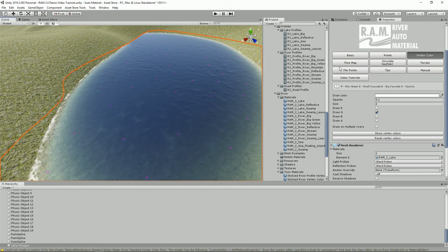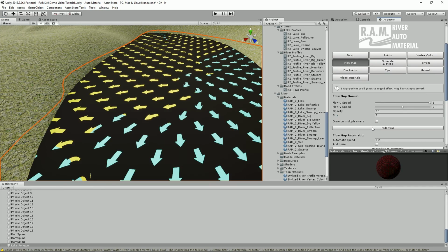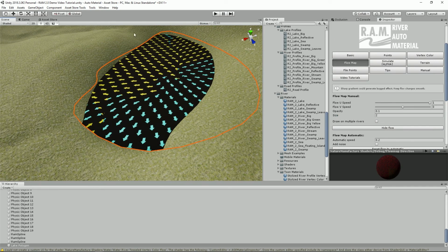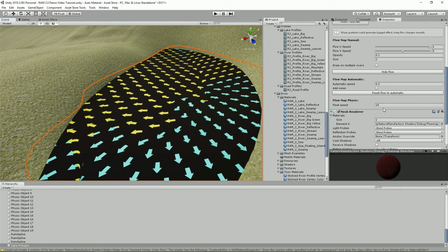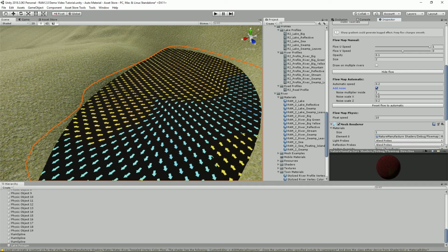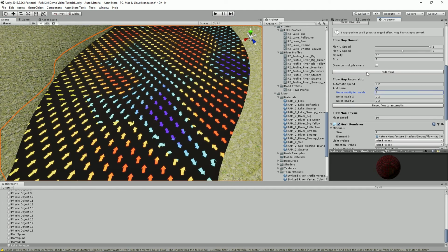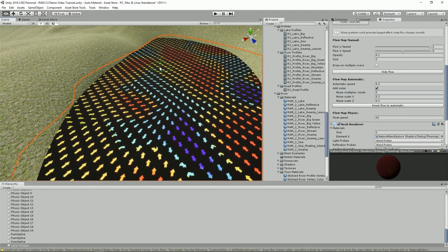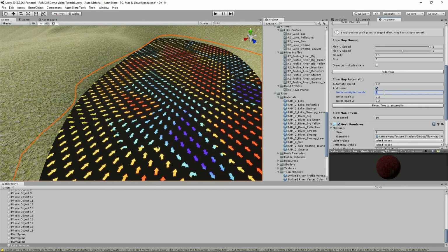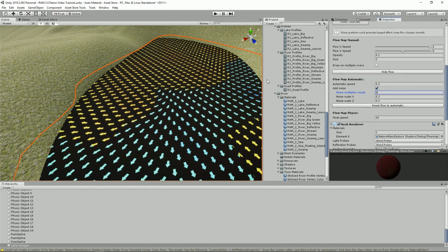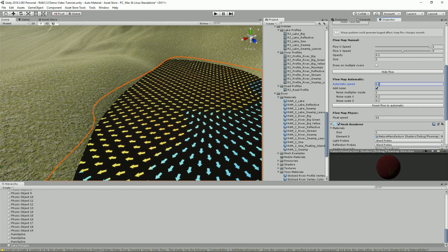If you look at the lake, we also have a Flowmap. We have a Flowmap, and water always moves from the middle to the lake borders, as we see on the Flowmap. There's noise also. We could add noise to our lake, but remember not to put it too strong, because we will get such a strange result. Water will be simply too fast, and the mixing in UV will be very strange. So we rather keep it very smooth at pretty low values, and then we have a nice result.